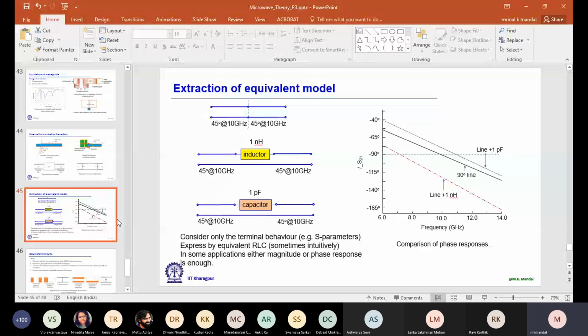Well, then the third point, how to obtain the equivalent circuit. Here we have a problem. For some simple cases, you can directly do it. For some complicated cases, the circuit is so complicated that it's really difficult to obtain an equivalent circuit. Sometimes it is a research topic for PhD students, particularly for active devices: what should be the equivalent circuit at microwave frequencies? Even the equivalent circuit will change with biasing voltage because it's nonlinear. So it is also a research topic for some PhD students.